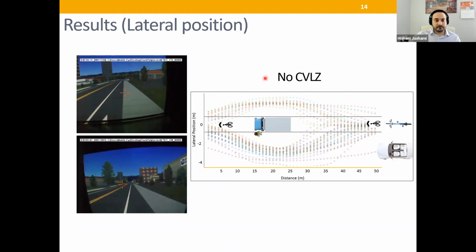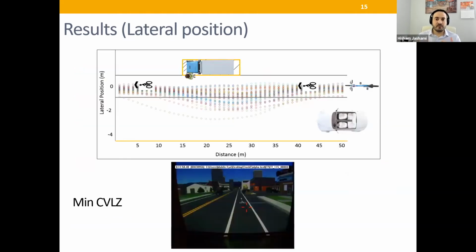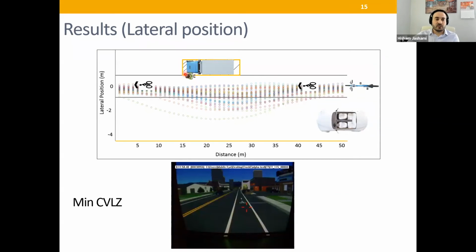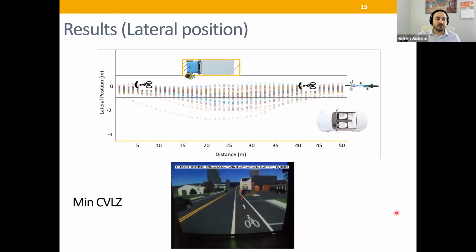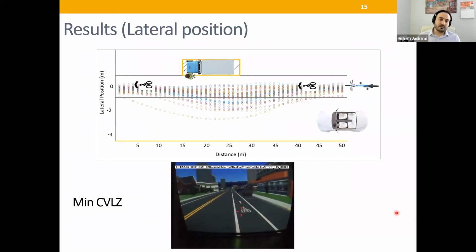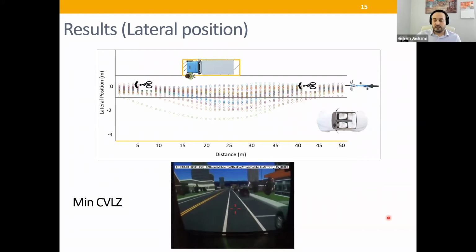And went back. Okay, for the minimum loading zone, several participants diverge from the bike lane, and this is due to carrier position. So they try to avoid them. But compared to the first case, they didn't diverge earlier or higher. So what I mean by this, if you can see here, they diverge earlier actually, while in this case, they diverge when they saw the driver walking towards them. Okay. So here is a video. So they saw the driver, they decreased their speed, and then they deviated towards the travel lane.